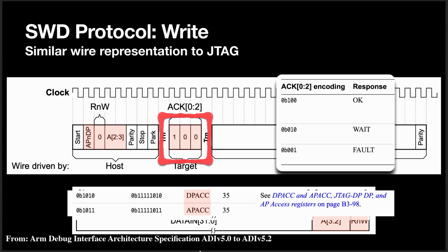But now instead of accessing a different JTAG address, we just have this 1 bit towards the beginning of the frame that sets the AP or the DP. So what they've done is they've taken everything you use as JTAG and just put it in one message that you send the target. Everything else just gets stuck in the data field, but everything else is actually identical between JTAG and SWD. The only difference is the framing that goes on beforehand, and the fact that it's on 2 wires rather than the 4 wires of JTAG.